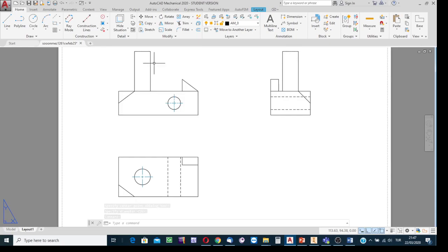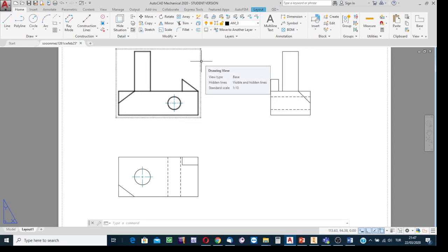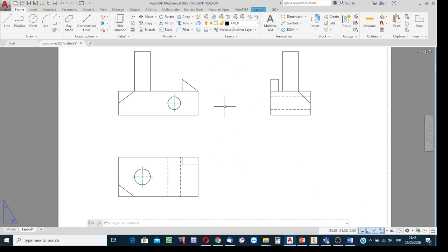Okay, to be able to highlight that this rectangle on this view, this rectangle on that view are the images of cylindrical extension, which is a revolved feature in general, we use longitudinal axis, show longitudinal axis. But since the views are not drafted but created ones, for creating the longitudinal axis, this command is to be written. Center line. Okay, select from the list the center line option, and then it is to say a longitudinal axis.